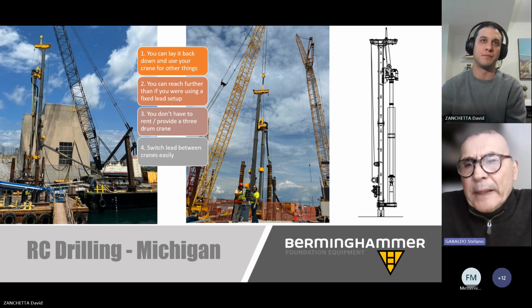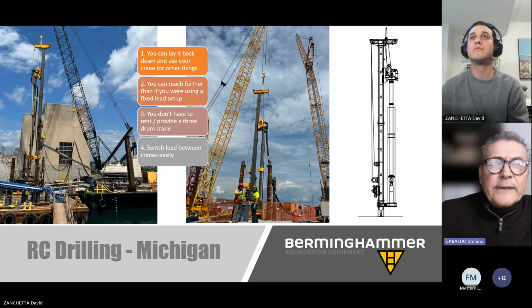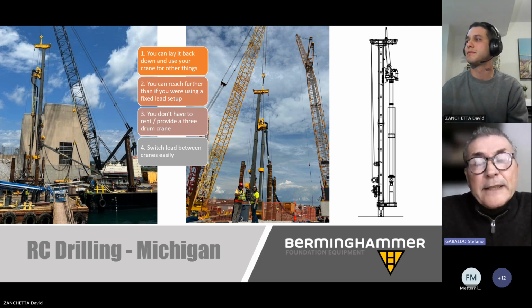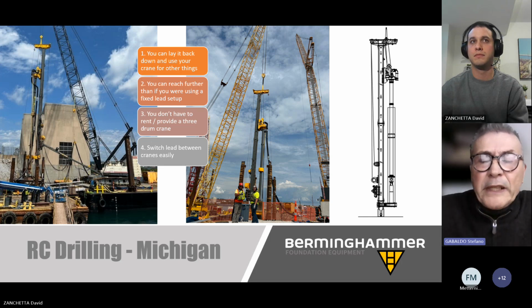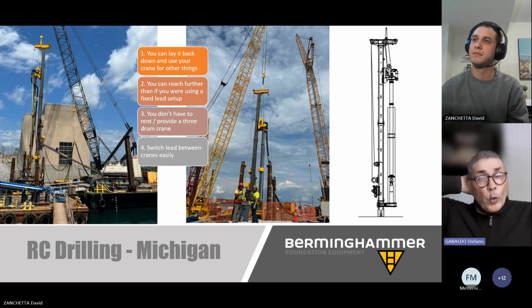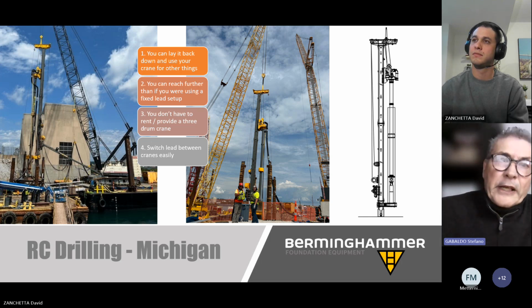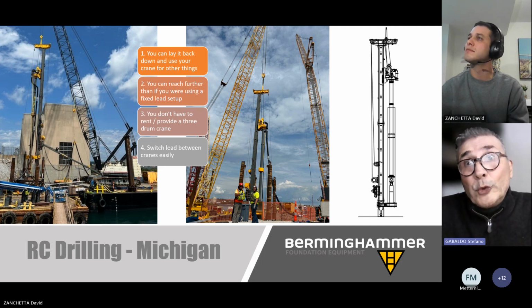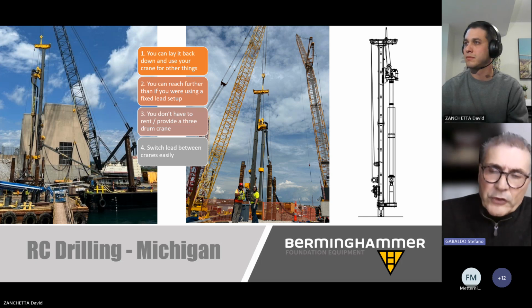Yes, it's a great question actually, because 200 feet of CFA is certainly a challenge. While the auger itself is on the lead, we can put provisions in order to maintain the alignment of the lead and the auger. Once we are into the ground, it becomes a little bit more challenging, and the driller experience comes into play. There are a lot of ways to minimize any deviation due to ground conditions.